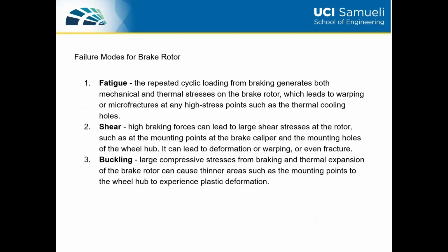Some of the failure modes for the brake rotor include fatigue, and this might be due to the repeated cyclic loading from braking, and shear, because those high braking forces can lead to very high shear forces at the mounting points. And then lastly, buckling, because of large compressive stresses from braking and the thermal expansion.